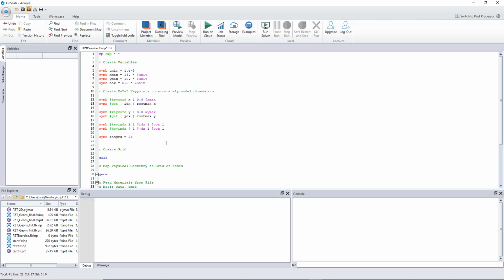So the values located in the idx variable will be basically the number of the last of the key points. So if I have 5 key points, idx will be equal to 5. So when the interpreter reads this variable, this idx is replaced automatically by 5, and this gets equal to the value saved into $I5. So that's how it works.